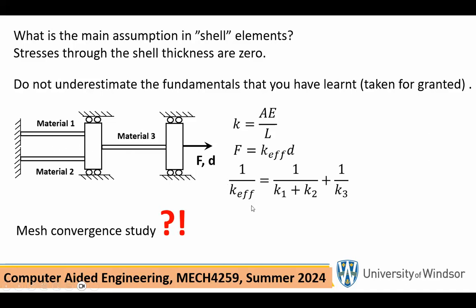All right. The other thing is that I've told you many times that if you make a single finite element run and look at the numbers and the colors, you might as well throw it in the garbage because it's totally useless. What one needs to do is to perform a mesh convergence study or a sensitivity study, and all that means with respect to mesh. Let's pretend that your modeling was okay. In other words, you did not make very dramatic assumptions that completely changed the nature of the problem.